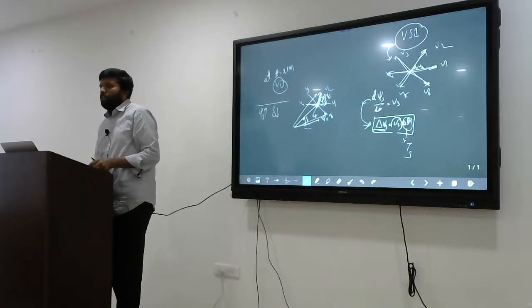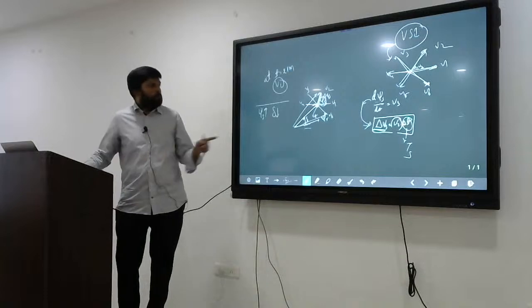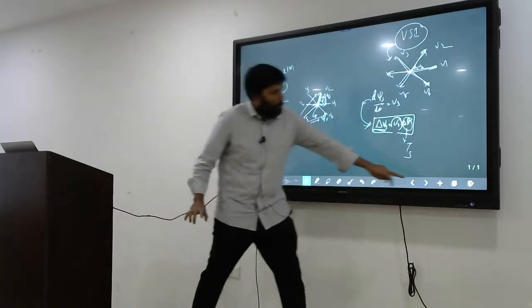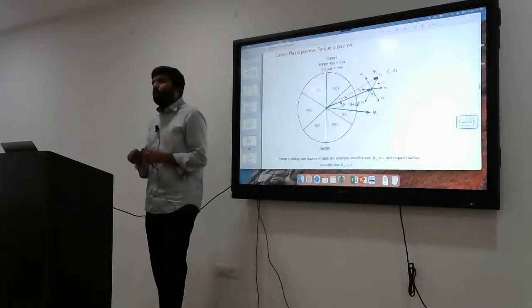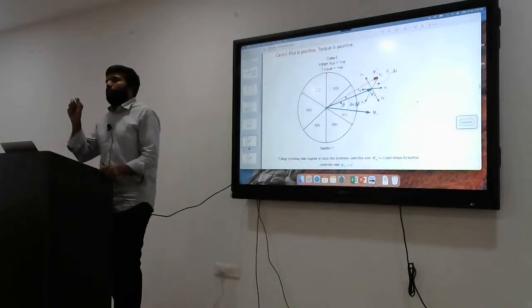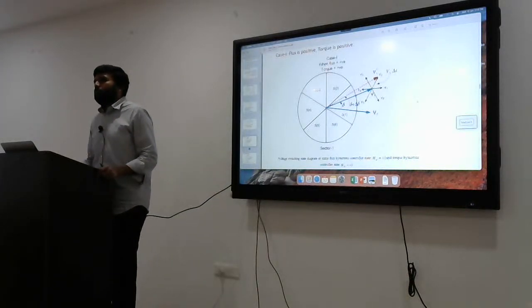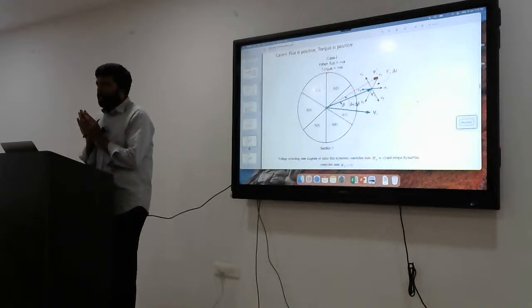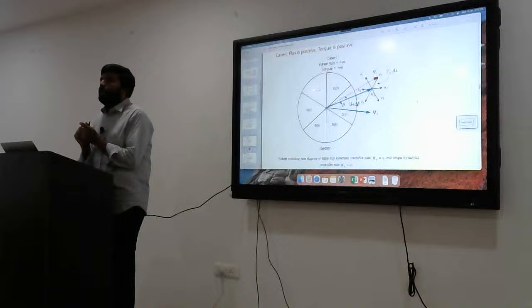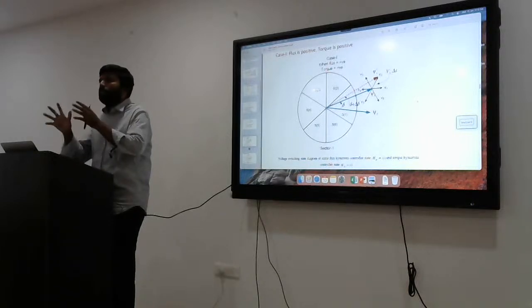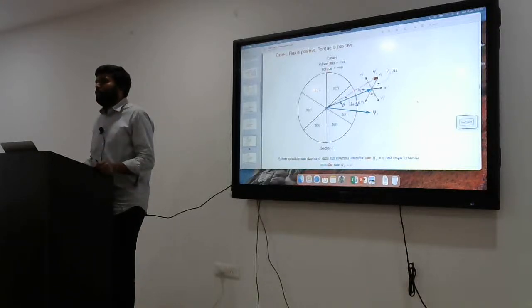See here, this is the phasor diagram of the three-phase induction motor by adopting the DTC method. It is a very simple concept. It doesn't require any three-phase to two-phase transformation. No Clarke, no Park, right? One more important thing is that this is not an indirect control. This is a direct torque control and direct flux control method.